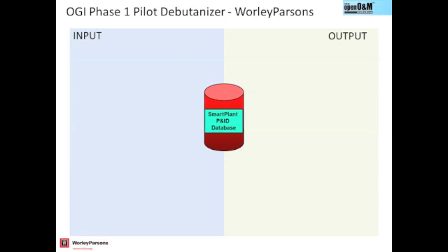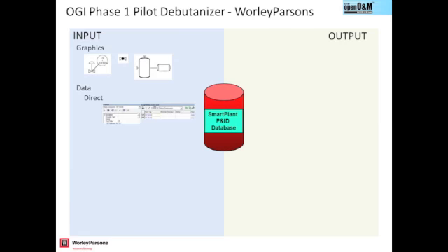The intelligent P&ID system that we're going to be talking about here is Smart Plant P&ID. It's a database-driven application. It has a series of inputs, and you get a whole series of outputs. The inputs are no different from a normal P&ID. You've got a whole lot of graphics, symbology, etc. It's standards-driven. The key difference here is you've got a data capability. We've got the ability to put in data associated with the P&ID: the instrument data, the equipment data, the line number data, etc.